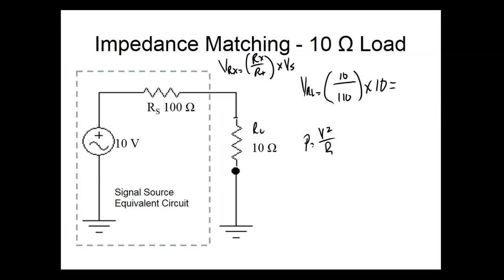Are we doing it a different way? We will call it IR drop. If you would have to find a current, and then from the current, you can do the IR drop. Yeah. So what happens though? You have 3 calculations. So we could do it this way. That's fine. So I could say 10 divided by 110, right? And this is 10 volts. Then I can take the current and multiply that times 10 and come up with the voltage. But what you're doing is you're adding another calculation.